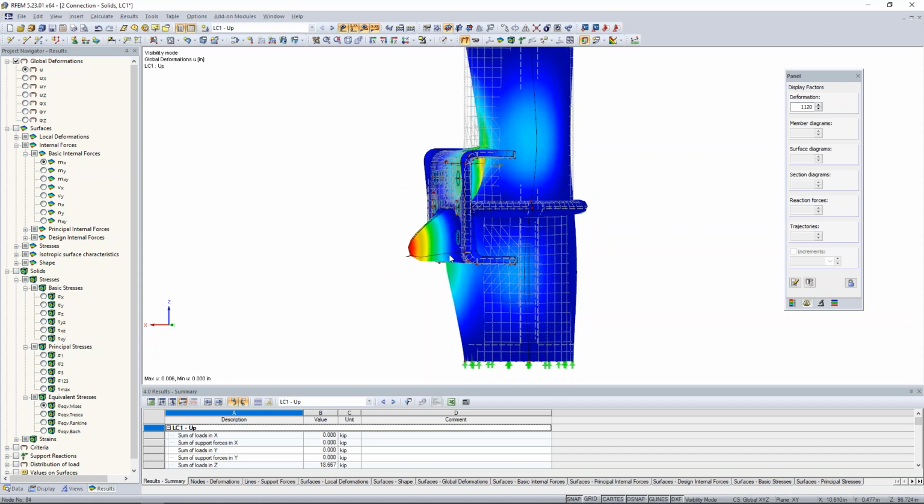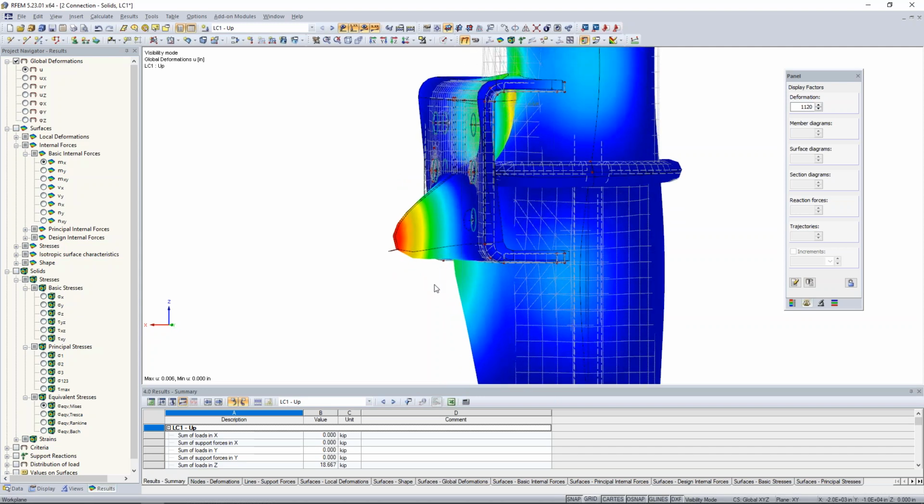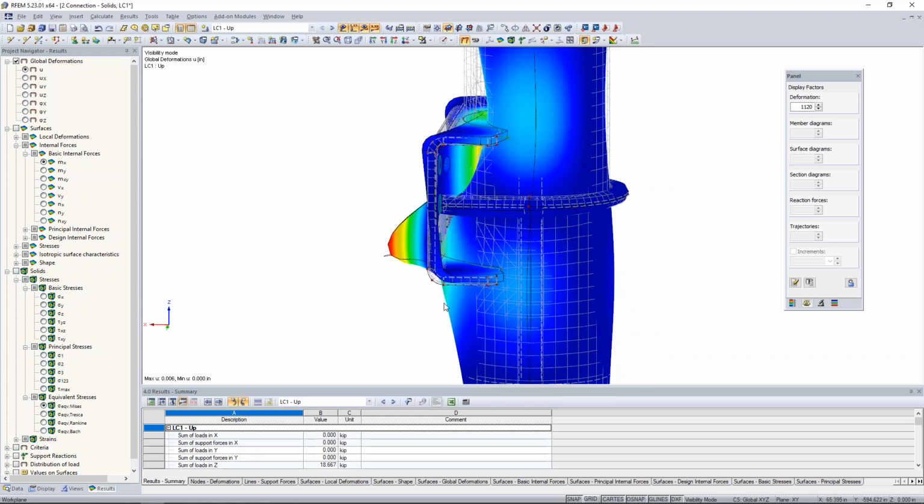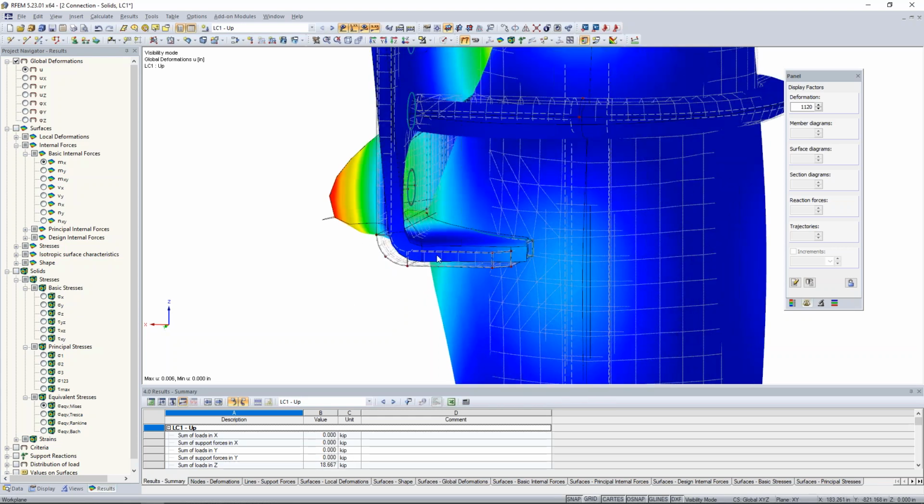So obviously we have tension on this plate. And because everything is fully connected here, you'll see this pipe element deformation following along with that plate. Everything is fully fixed. But in reality, we know that this plate is not going to be welded to this pipe. It's actually just sitting there. So in the event of tension, we'd actually like the full force transmission here to be released. We want this to be a failure between these two elements.